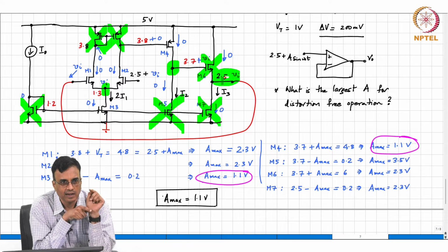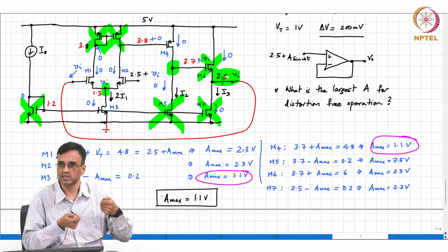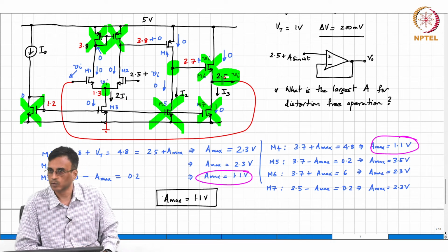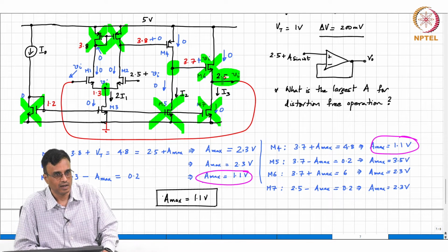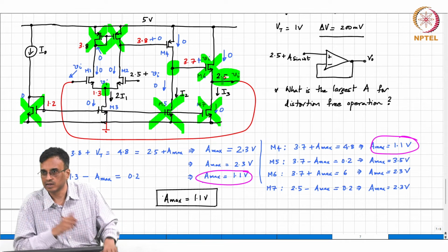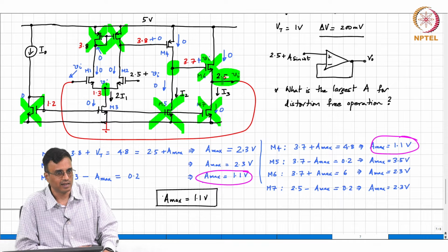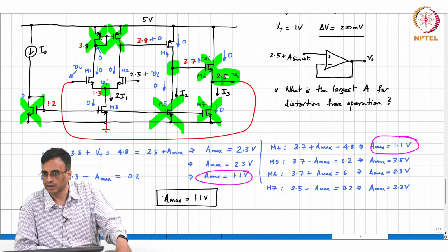One problem with our model for the MOSFET is that we assume that you apply VGS and drain current immediately flows, right. Without going into any detailed physics, if somebody told you that you apply a voltage and instantaneously current starts flowing, you will say nice try, correct, okay. So every stage, every transistor, is associated with a delay, in vague terms, okay.